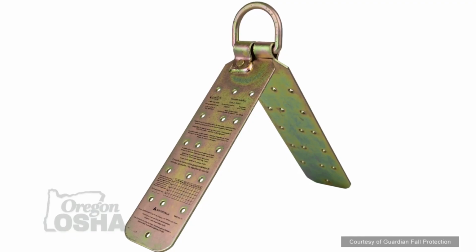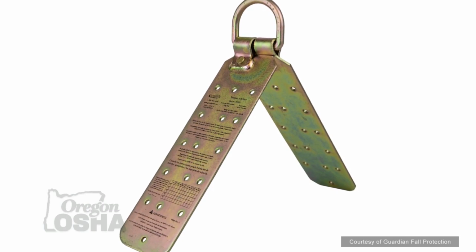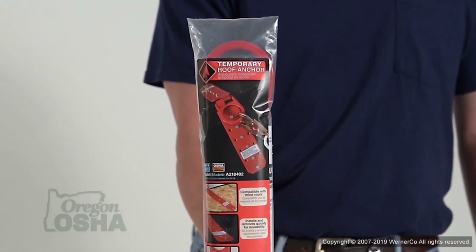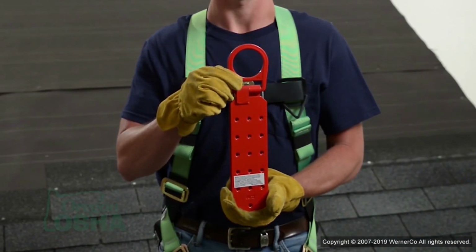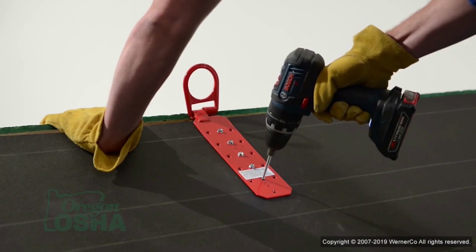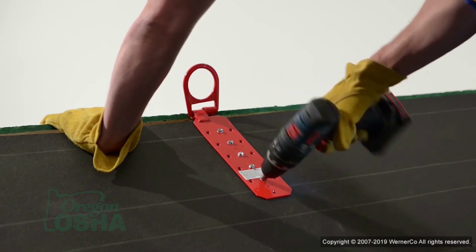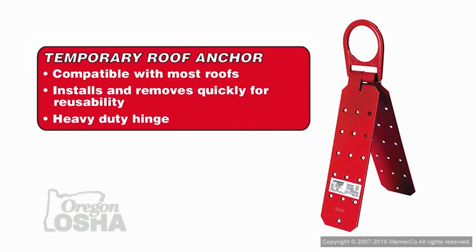So when it comes to the installation of your roof anchors, again, you got to follow the manufacturer's guidelines. They will specify whether it needs to be 5/8 plywood with blocking underneath, or whether it needs to go directly into a rafter, how many fasteners, because based on the pull rating of that anchor, different fasteners and different numbers of fasteners are needed, and so each manufacturer and each application is going to have its own requirements that you have to know, and you have to follow those specifications.